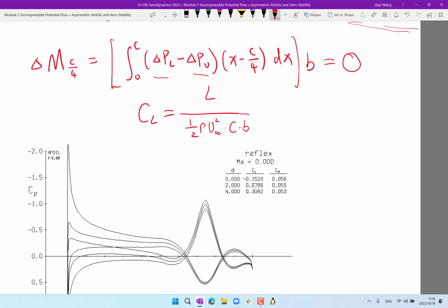right? So that's the lift coefficient. On the other hand, CM, the moment coefficient, is equal to the moment around the quarter chord. When you say the moment coefficient, by default, it is around the quarter chord of the wing. And if the wing is swept, it's the chord-weighted average of the quarter chord. Okay, so half of rho u infinity squared and c, b.